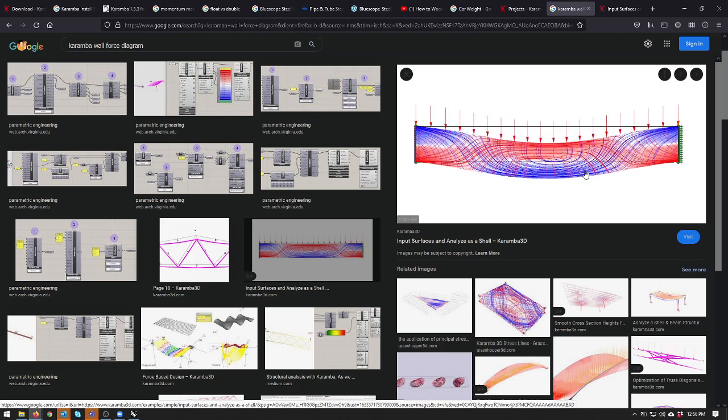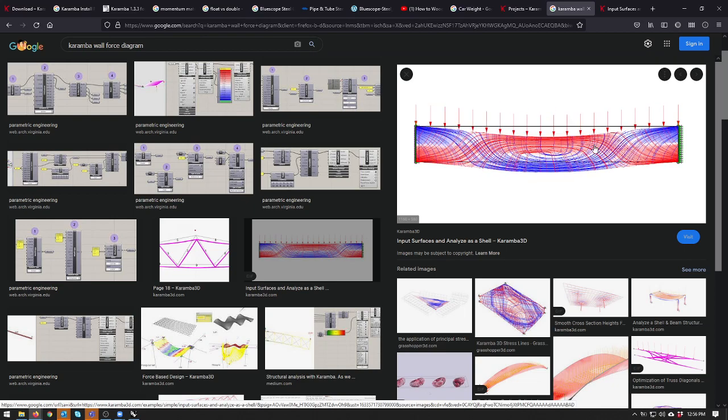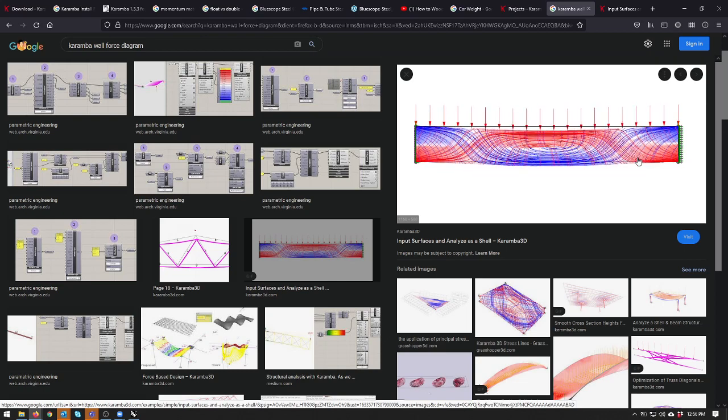Normally we would fill that concrete wall with just a simple grid of rebar, and the rebar would be excessive. What we're saying is the rebar in that concrete wall, rebar being steel, right? Just to double check with you guys. The rebar in this section and in this section and in this section would be wasted. It's effectively just there because we're doing brute force structural support there, whilst the rebar effectively allows the concrete wall to deal with tension. So all of these elements that are in tension, that's where the rebar is actually being formed.